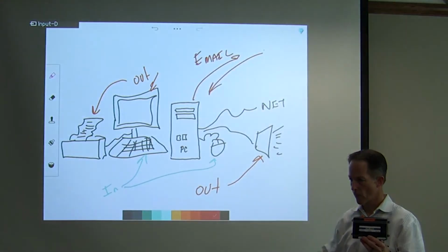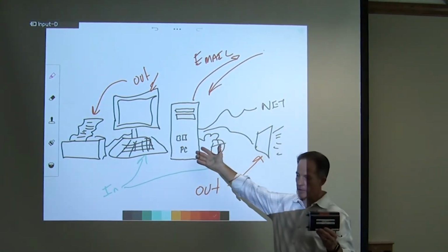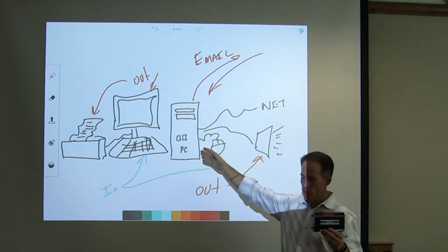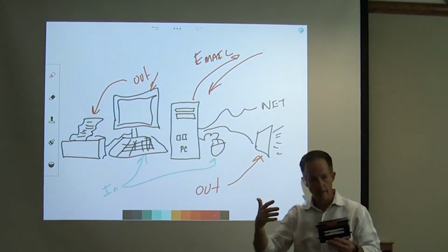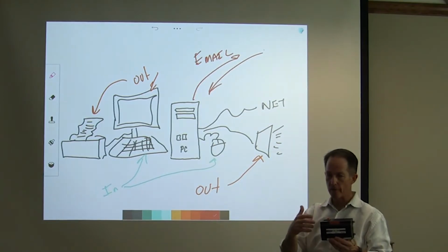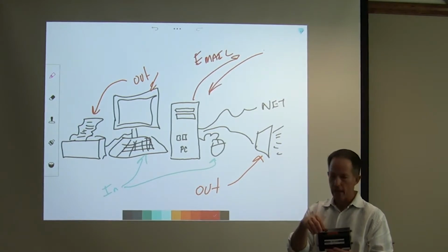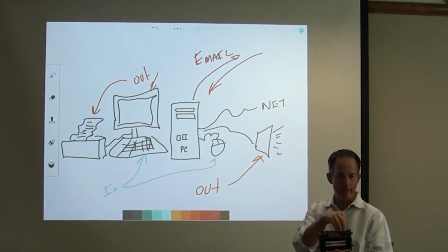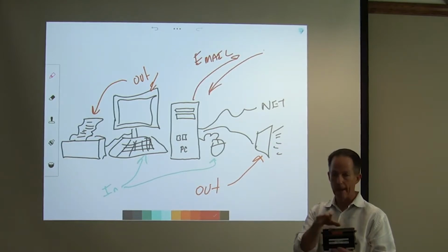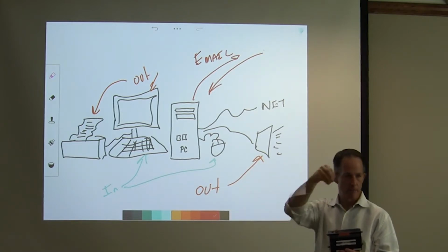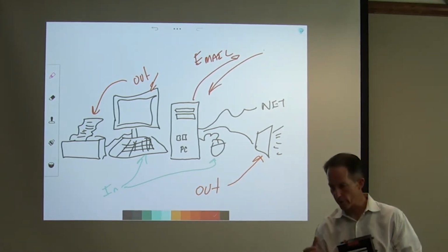And then on the Niagara network, on the supervisor, you open up the graphic and install a point on the graphic that's connected to that other point. So back on our supervisor, there's software running there. That software has the ability to discover the JACE, or to identify where the JACE is, and then to see what points or devices the JACE is monitoring and managing. Then you add a point there. It's kind of a leapfrog thing that we do, and we pull that into the supervisor.